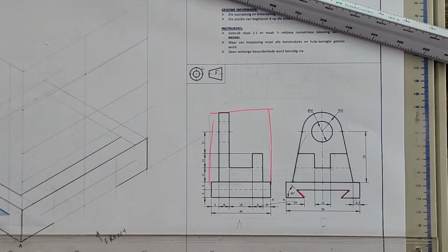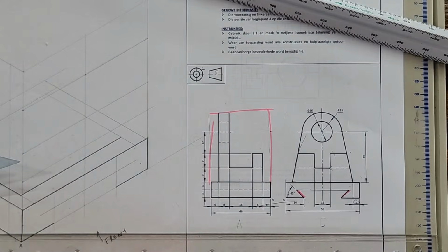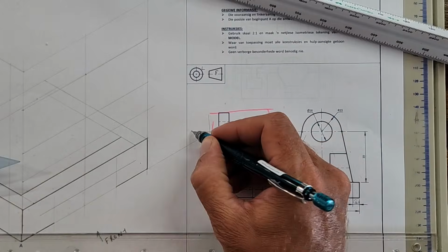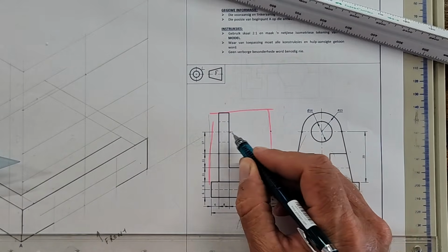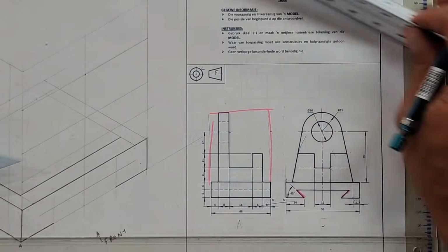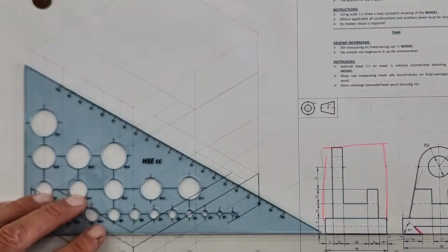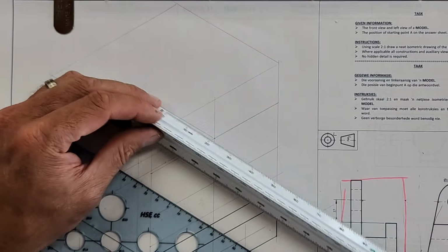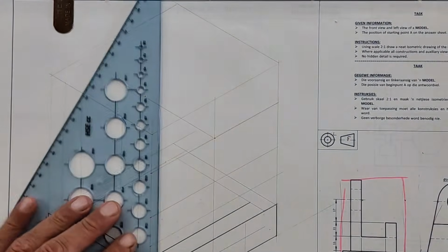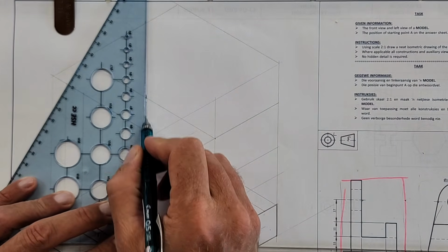Okay. So the center that we have here is in fact this center that's right here on the front, in the middle. There's a glass box around it. So that point needs to go backward. We know where that point is. We just need to determine the distance back. It's that 6 plus 8 plus 18. So it's 14 plus, it's 32. So on this one, construction line, take my 32. But I'm going to do a nice center line for me here.